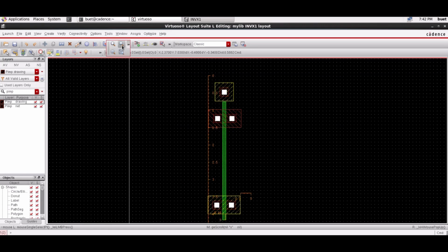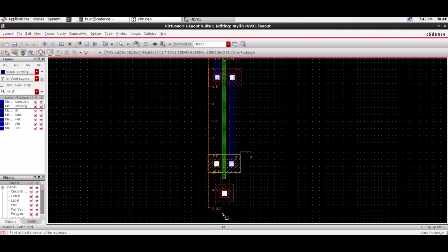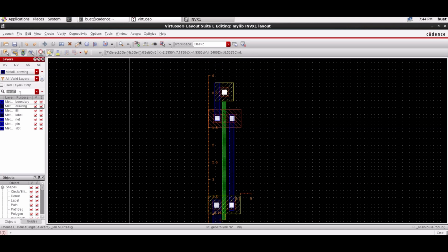Now connect the drain regions of NMOS and PMOS. Also connect the source of both MOSs to respective body terminals using this metal one layer. Then connect the drains of MOSs using metal one layer. PMOS should be in N-well, so draw an N-well rectangle surrounding both the PMOS and the body contact for PMOS. The layout will look something like this now.